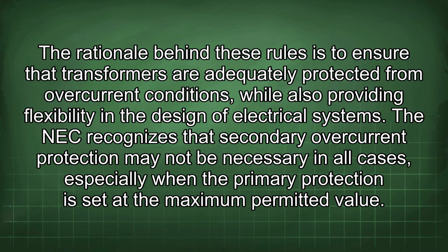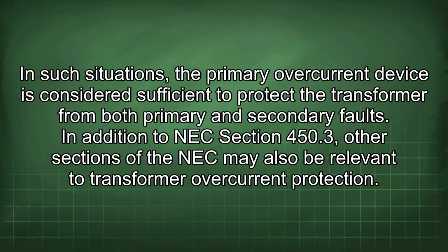The NEC recognizes that secondary overcurrent protection may not be necessary in all cases, especially when the primary protection is set at the maximum permitted value. In such situations, the primary overcurrent device is considered sufficient to protect the transformer from both primary and secondary faults.